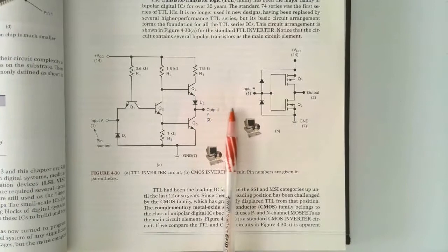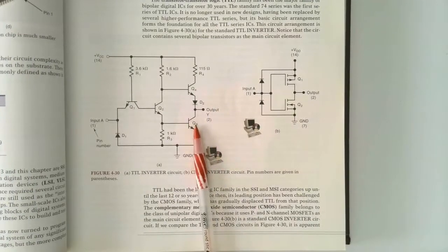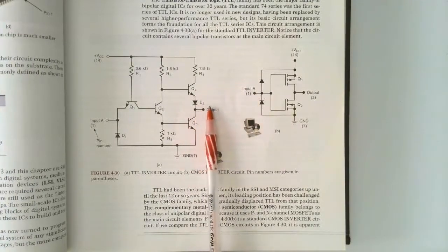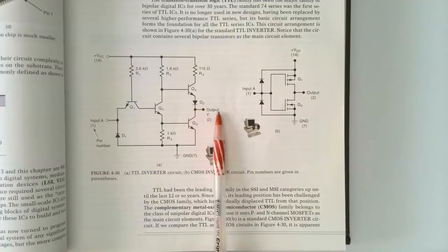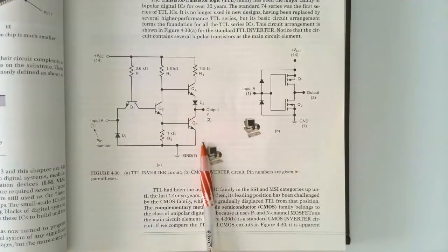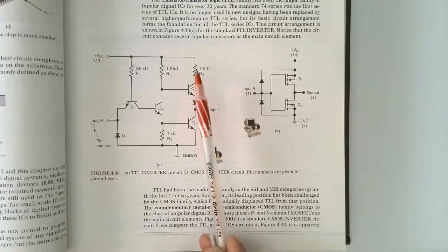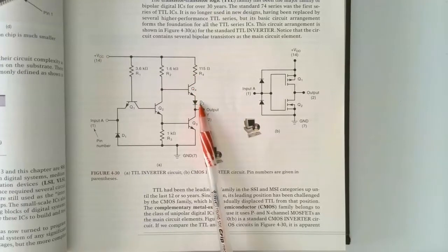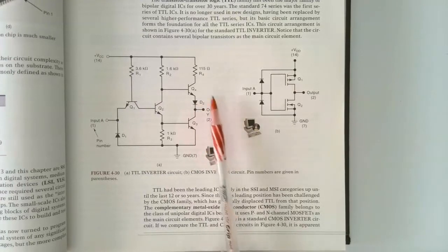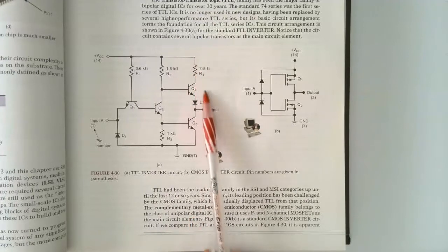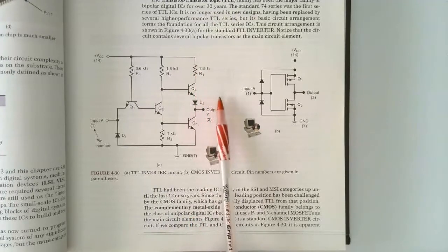We'd have current flowing out. If Q3 was on and Q4 was off, basically nothing is connected above that point and all of the current goes to ground. But what's important here is that there are voltage drops across this resistor, across the transistor, and the diode for a high output voltage. And what that basically does is it takes away from the 5-volt output, reducing it to something on the order of between 3 and 4 volts.